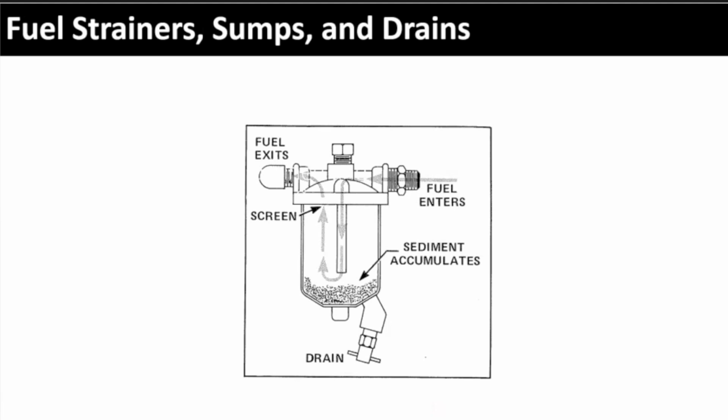The 3 in the bottom make more sense, right? Because they're going through the final strainer and the sumps and everything. 5 in the tank itself, I don't know. Is it because maybe they created a tank with 5 low points? I don't know. My guess is that the angle of the wing isn't as steep as compared to a low wing. Yeah, I don't know. I think there's 2 closest to the fuselage and 3 a little bit outboard. Right, so it's not even like they're all the way out through the tank. It's 2 and 3 in parallel. So yeah, I'm not the design engineer. I can't tell you why, but I would say test it.